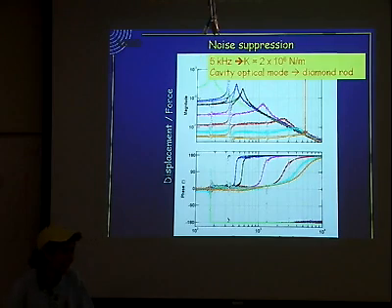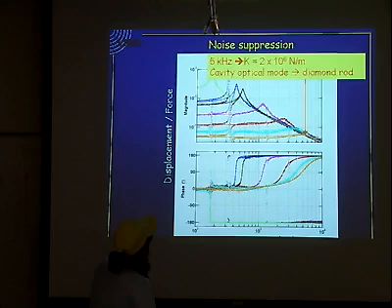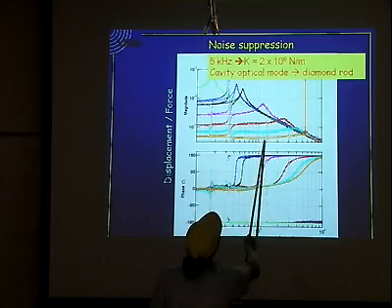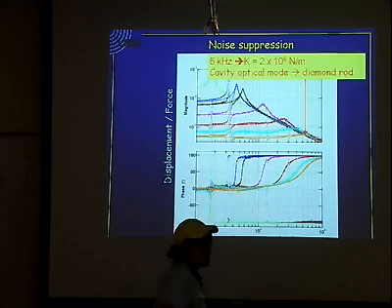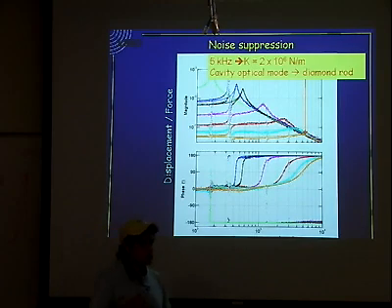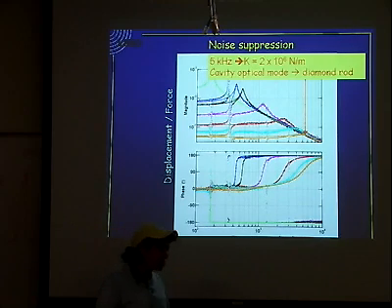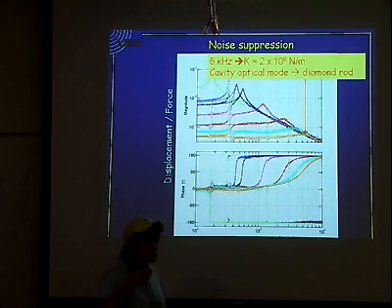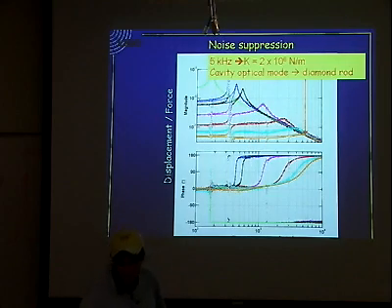What's that? Yeah. What's going on at 1400 hertz? At 1400 hertz. Yes, so that is another spurious mode. We have mechanical modes. And one thing we don't know about with this shell that it's mounted on, we think it's a mode of that, but we're not sure. But anywhere where you see those things, those are spurious modes that shouldn't show up in the measurement.